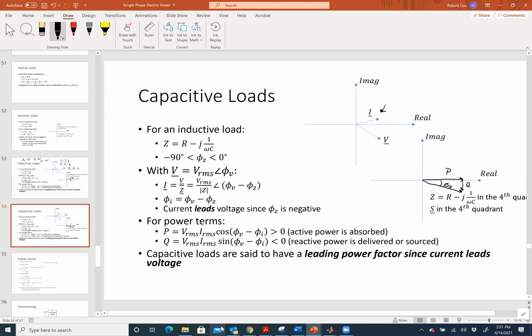So it's heating, air conditioning, all that kind of stuff, right? Lights. For the most part, those loads are inductive loads. All right, so utilities will put capacitors out there to maybe help with those loads, to source things to those loads. All right, so we have this term leading power factor, lagging power factor.